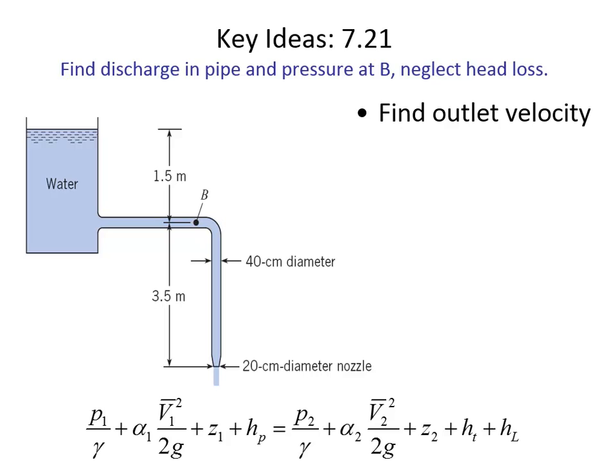And so this is essentially acting as an orifice. So you can find the flow rate out using the orifice equation. You know the cross-sectional area of the opening. And remember the orifice equation, velocity is the square root of 2gh. So how do you find the flow rate from that? If you want Q, then Q is A times the square root of 2gh. So you can find the flow rate by the change in elevation and knowing the characteristics of that opening.